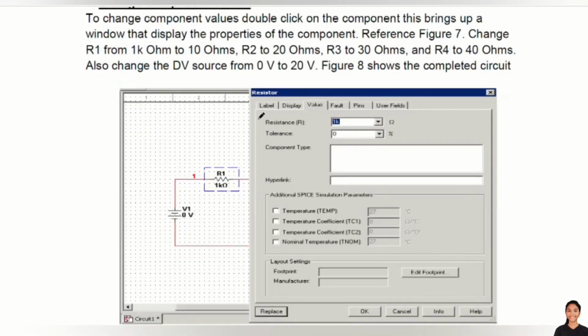So if you already placed this resistor but you want 10 kilo ohm, for example here I have selected 1 kilo ohm but I want to select the 10 kilo ohm, you just have to give a double click on the component, then this box will open and you can search for whatever component, whatever value you want to change, just change it here.